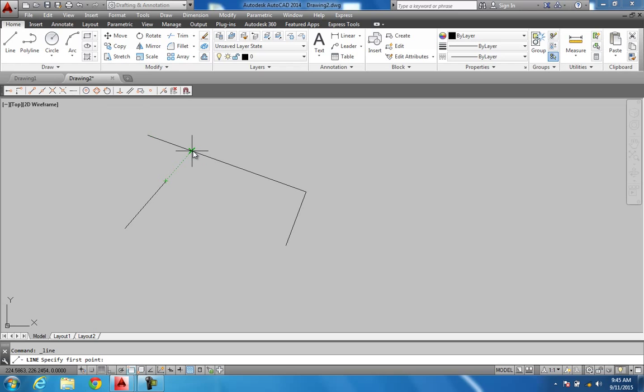You see how it does an apparent intersection? Now you've got center here, and I had that one turned on down here in my object snap. If I wanted to put a line, go to center, see how it catches my center point. This is quadrant, and your quads are around the 4 90-degree points of your circle.